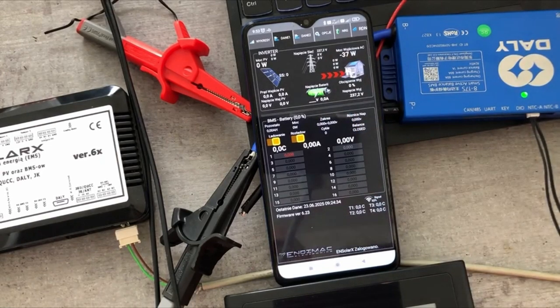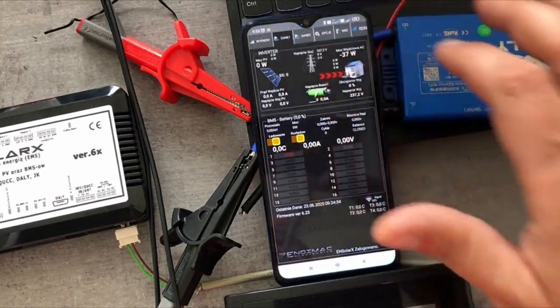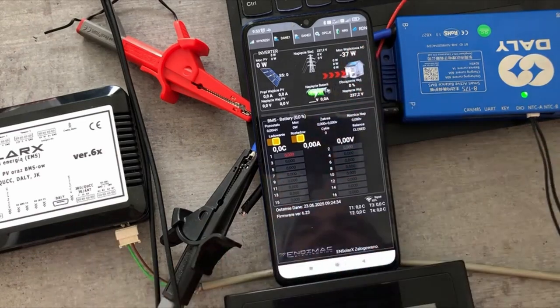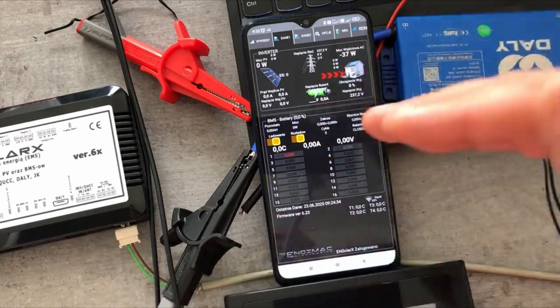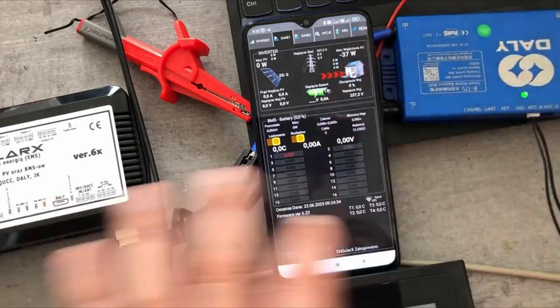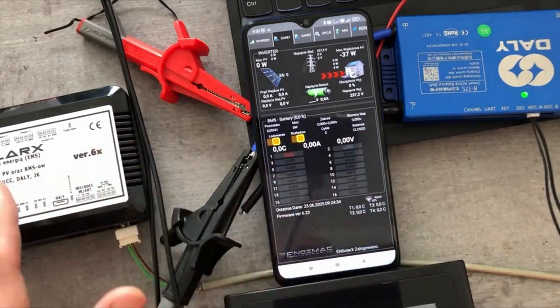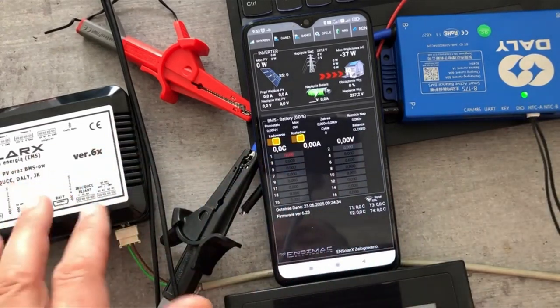Only you can see it's connected to an external energy meter. It picks up here minus 37 watts. This means that it draws 37 watts from the network. And this gave us this information: a three-phase meter, a small one on RS485, and this is where this data came from. That's why you can see whether something is being sent to the network or received.